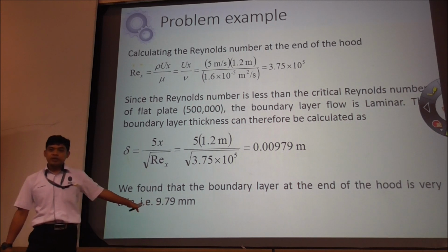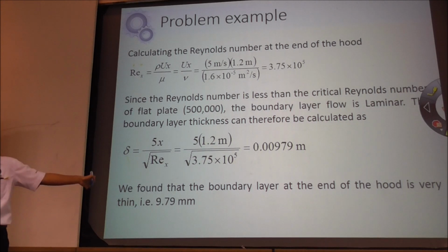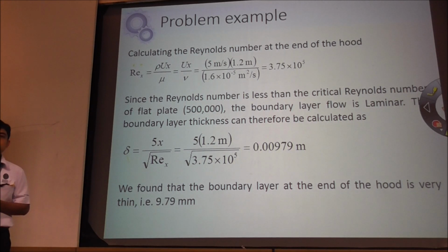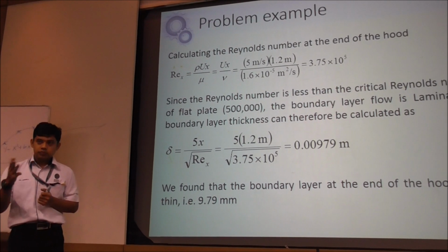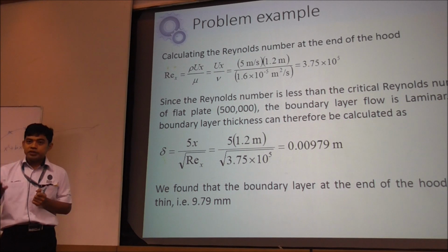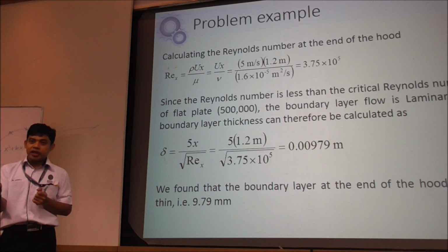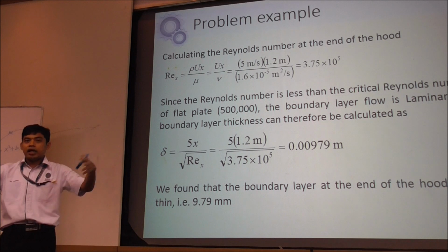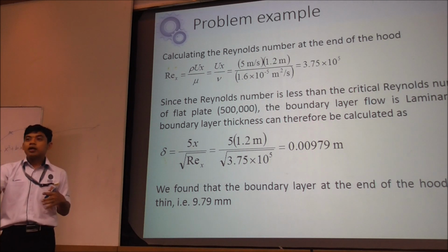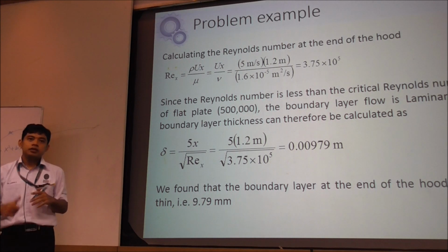Okay, the next question I can ask you is, what is the shear stress acting on the hood? You need to find the coefficient of friction. Once you get your coefficient of friction, you can calculate your shear stress. When you calculate your shear stress, if you know the area, you can calculate the force. The force times the velocity, you get the power.